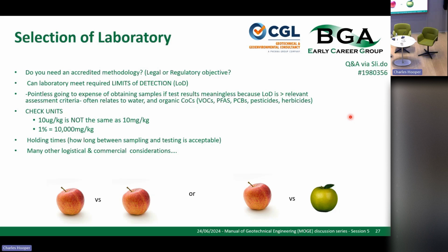Holding times, which is the time between your sampling and your testing, that was one of the issues when you look at the E. coli testing and bacterial testing, is how long have you got between you taking that sample, packaging it up, putting it in your cool box, carrying it from wherever you've sampled it back to the lab. The lab then will book it in, process it, put it into their processing system. That might take some time.